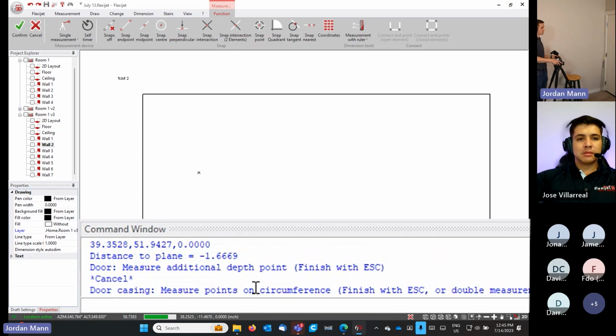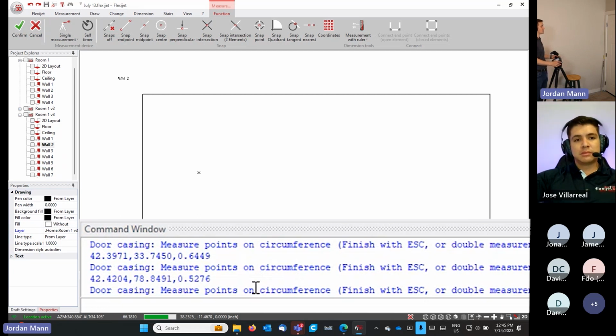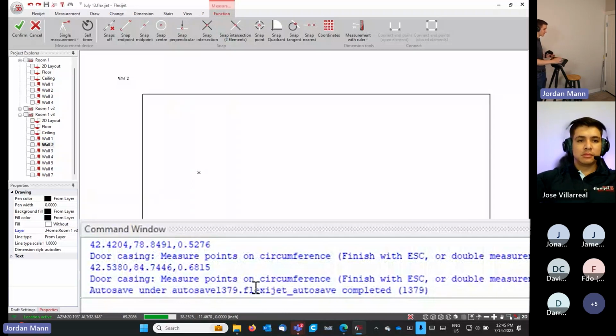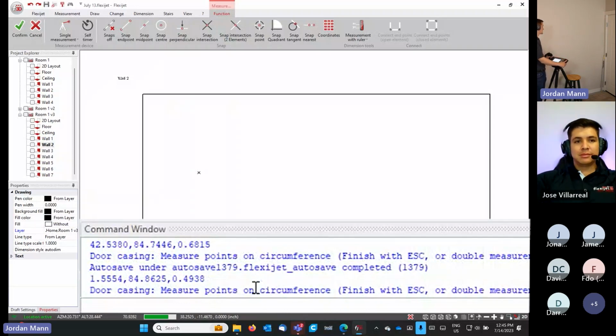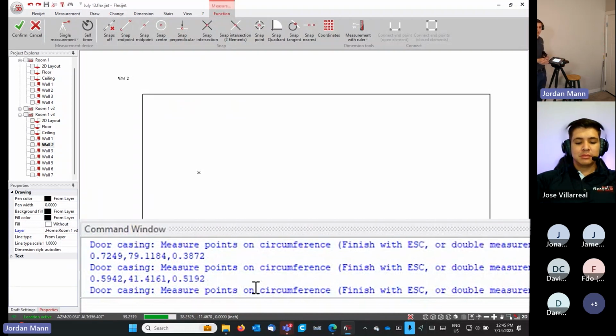Measure points on the door casing. So same thing here again. The most accurate would be to get over there with the target and measure these points. I'm going to just aim the laser near the edge. And for those of you that are used to measuring for glass and countertops, you're probably cringing a little bit, but I assure you, for architectural measurements, it's a different ballgame. The accuracy that the architect may be requiring for this may be met by what we're doing here. The output of your project will determine these things.